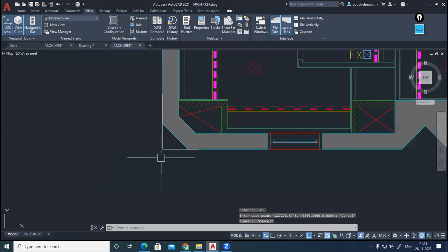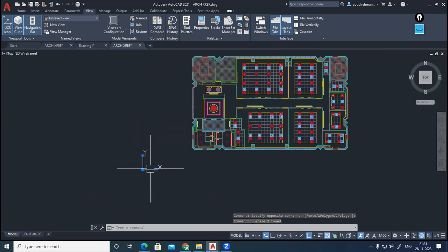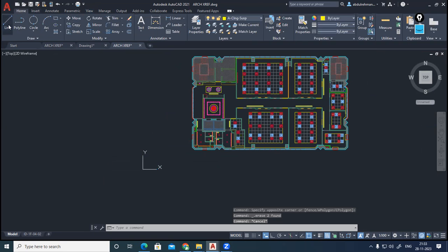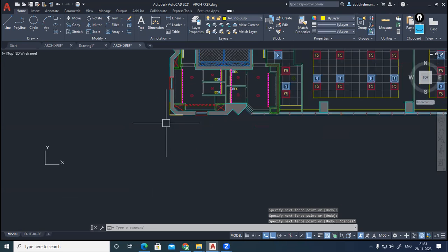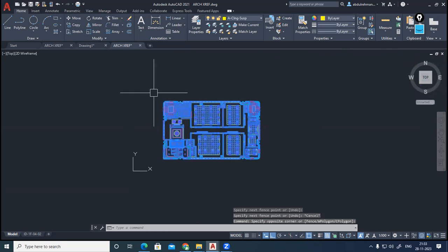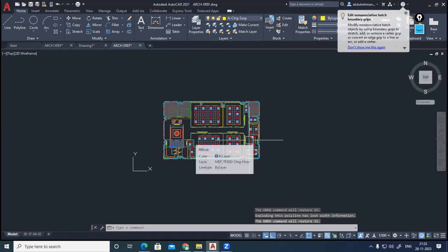Okay, so what I'm doing is placing this exactly on the origin. This is my 0, 0 point now. If you have doubt, select a line, then 0, 0. That will be starting from the 0. So I'll be making a reference line from here, and one reference line from here as well. Now the unnecessary lines you can trim. TR, double enter. Then this one I'll be placing there. At the same time, I'm exploding it. This job has to be done by the architect.